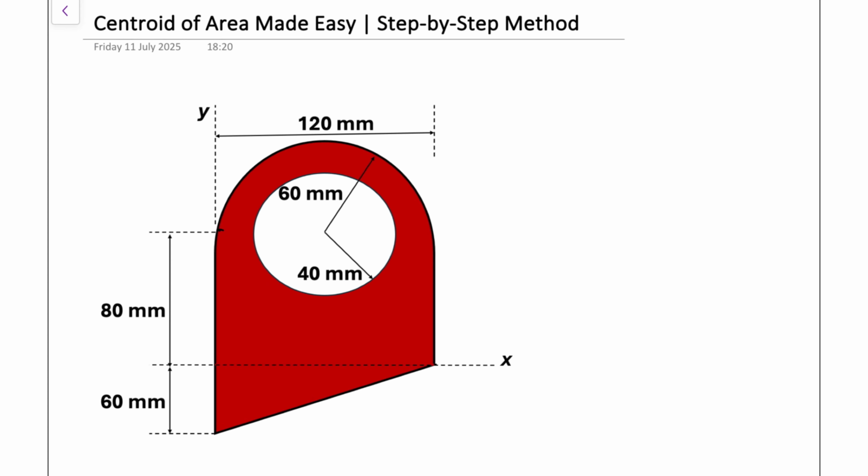And the best analogy I can give you is when we were looking at finding the moment for different beams or the reaction forces, what we had was, let's say we have this beam and we have a pin joint there, let's say a roller there. But what we had in terms of loads, we had this UDL, so that uniformly distributed load.